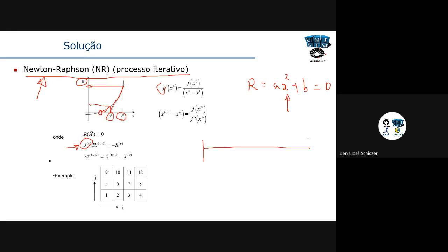If I have a time step, for example, of 30 days, and I'm trying to find the solution for the next 30 days, and I try to converge these equations in 10 iterations and don't reach convergence, that means the solution is not converging. So what the simulation does is go back to the original point and cut the time step in half, in this case to 15 days.